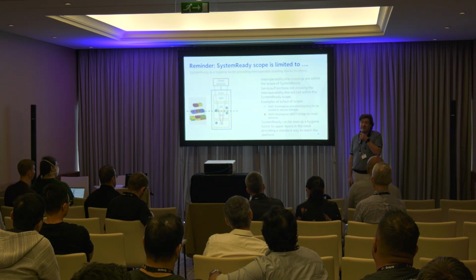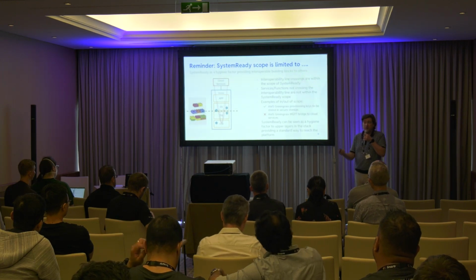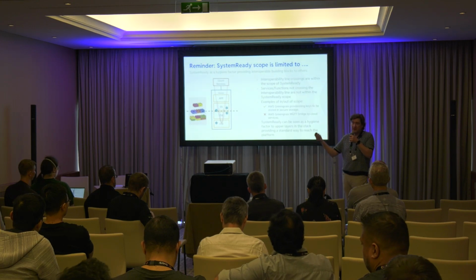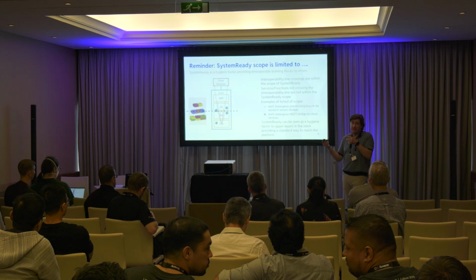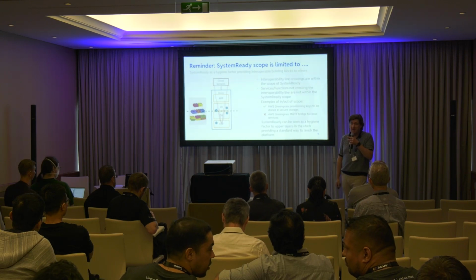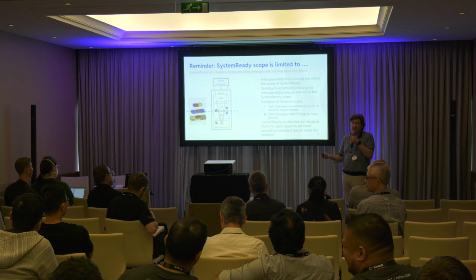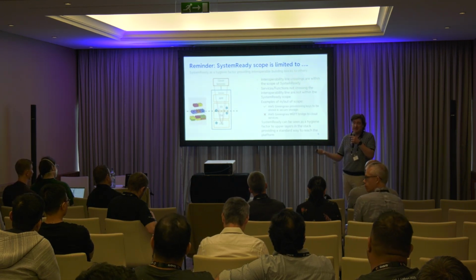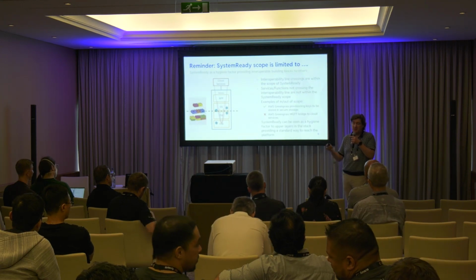If you're thinking about Devicetree, it's not only about booting, it's more than booting. If you have a graph, every node in your Devicetree that is supposed to be visible and accessible from the OS, we have an obligation to provide integrity checks for it. So if you have a GPU or graphics, you have to make sure that the driver is properly linked to a node, it's been loaded, it's been initialized, and it is there. We are not going to check the performance of the GPU.